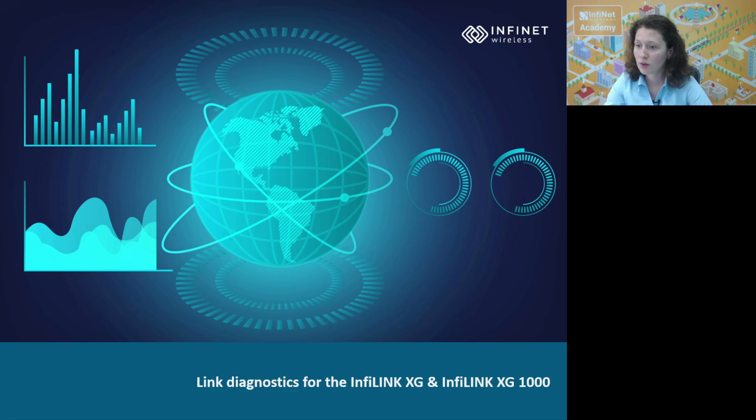Next, we are also asked about the pulses. You should keep in mind that the XG does not support pulse detection like we have on the R5000 devices. You now only monitor the CINR and RSSI levels using the tools that we have and the status section.